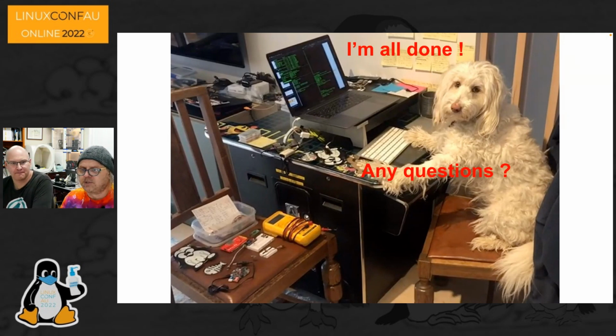There's initializing these peripherals, and then sending I2C commands to set the DAC is really easy to use. It's basically one command to set the voltage for one channel. So with 2 commands you can change the voltage on the 2 channels for the front end.